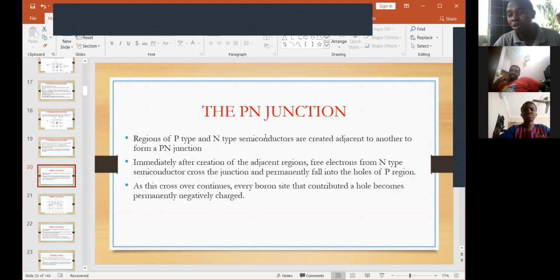Because it's a combination. So if you want to build a 30 volt system, because one of the things we'll be doing in this class is that, tell me any panel you want to build in this world, I will tell you how to go about it. I'll tell you the combination of what you do. If you need 100 watts at 200 volts, I'll still design it for you. This is a 100 watt panel at 18 volts. If you still need 100 watts at 200 volts, it's still possible.